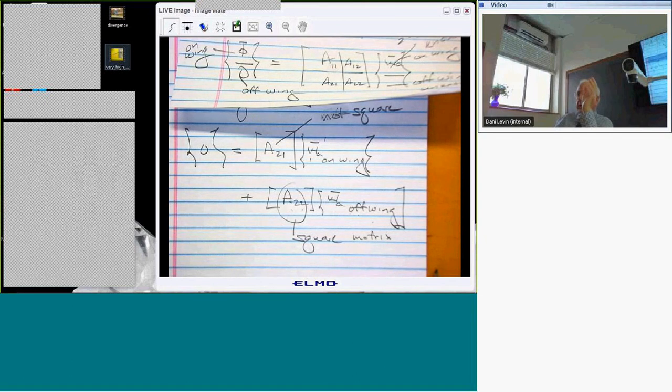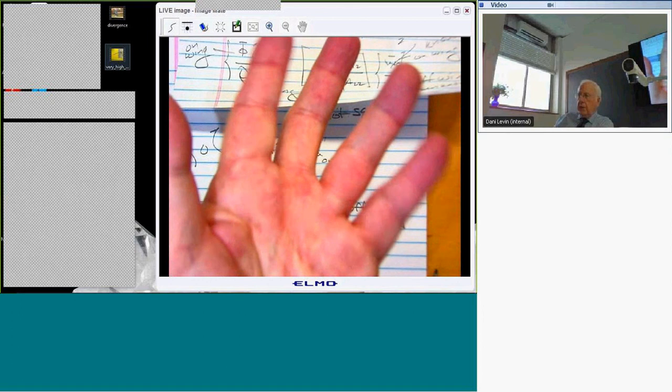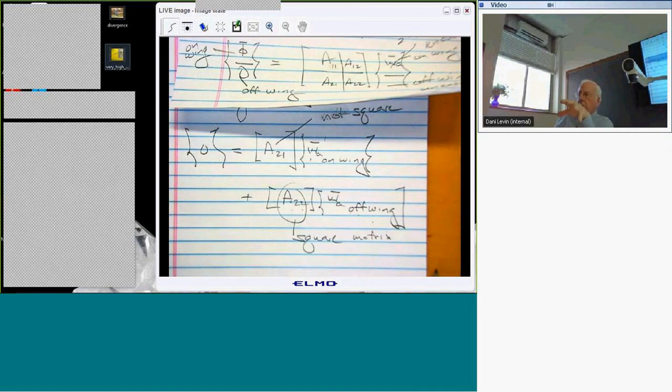So if you try to do something like this, you would first of all take a Fourier transform with respect to x now, and a Fourier transform with respect to y, which would be fine. And then you could get a formulation just like what I've discussed. When you did the inverse, you would discover the inverse in subsonic flow looks different from the inverse in supersonic flow, but you could do it. But there is a slight practical problem. The flow is disturbed everywhere in the plane z equals 0. Everywhere, right on out to infinity. So you're going to need a lot of boxes. In fact, if you watch closely in supersonic flow, when the Mach number went to 1, remember there's that beta factor?